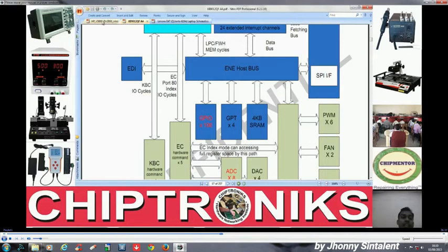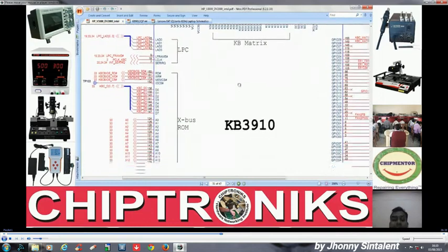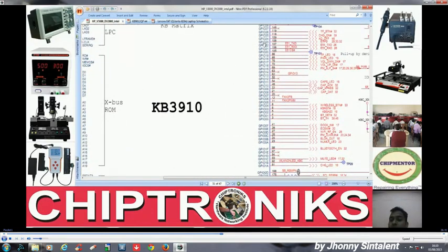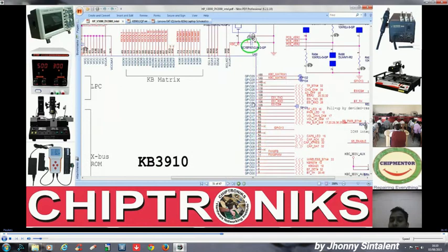Let's see with DV2000, you can see these GPIO. These are all GPIO. Some of the GPIOs are not used, so a cross is there, and some of them are test points. You see TP102, TP104. Some of them are configured as input and some as output.